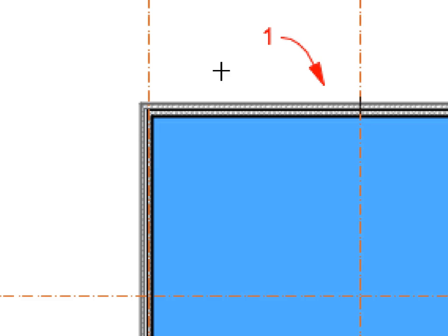of the mass polygon. Please remember, when you keep the spacebar pressed while clicking an element edge, ArchiCAD will take any consecutive path of edges the clicked edge is part of and will use that polyline for the geometry of the newly created element. In this case, we have the Wall tool active, so it will create walls. The consecutive reference lines of those walls will now lie along the contour of the mass polygon.